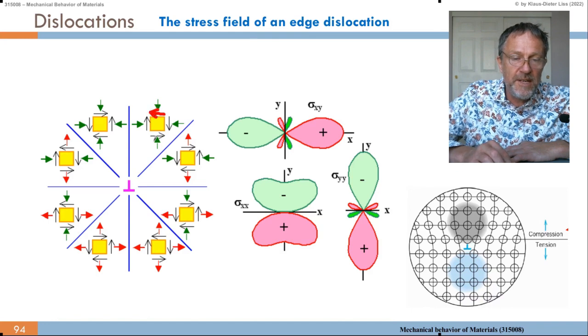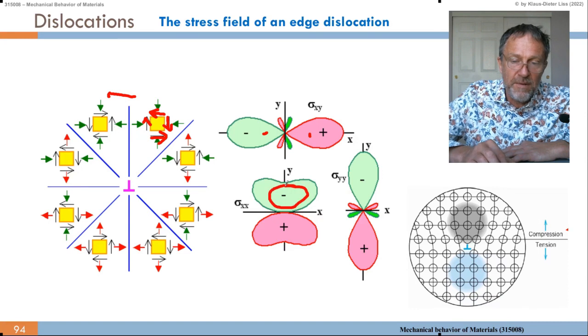Here we have the shear component like that, and shear component like that. Of course, sigma xy equals sigma yx because of the symmetry of the tensor. And if we go to the left side here, then it just turns around. So that goes from the positive to the negative shear, but both normal stresses, they are compressive.